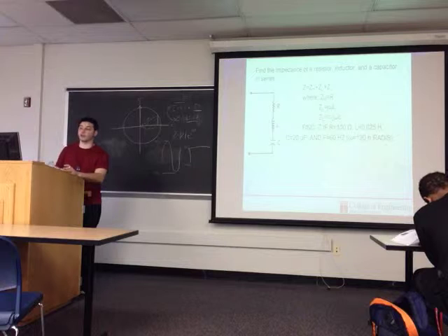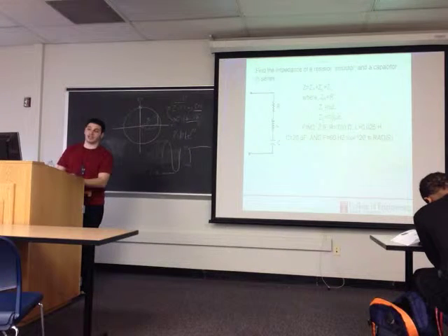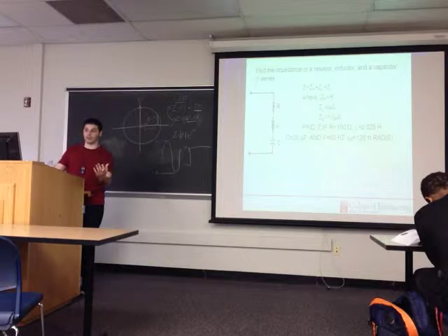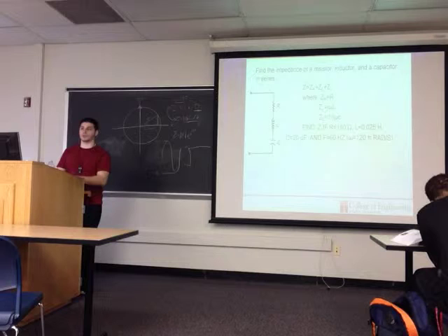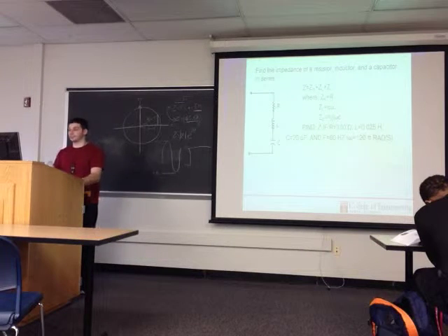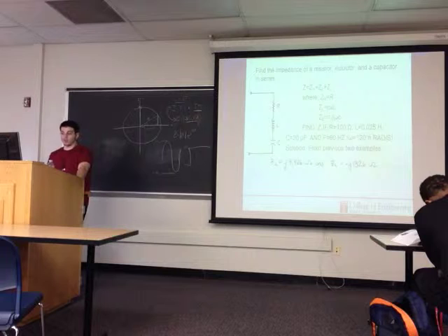well, we can, because these are all impedances, right? So these are all representing impedances, which are units of ohms. But it's complex ohms. So we're going to have a real part and a complex part, so it's going to be a complex impedance. So essentially it's the solution from the previous parts, right? So we know Z of L is equal to this, and Z of C is equal to that.